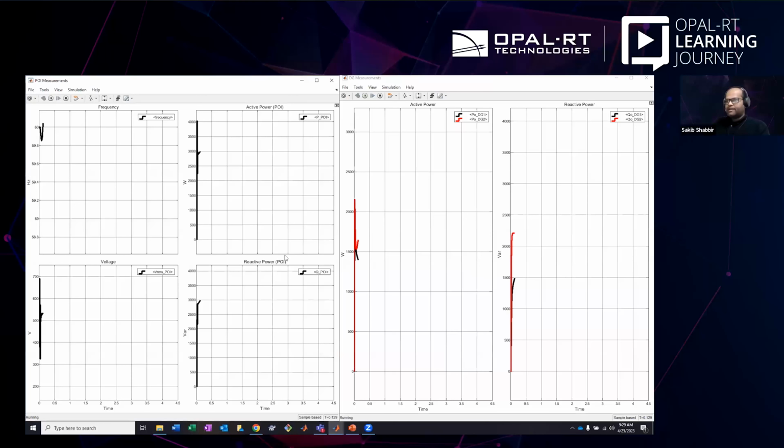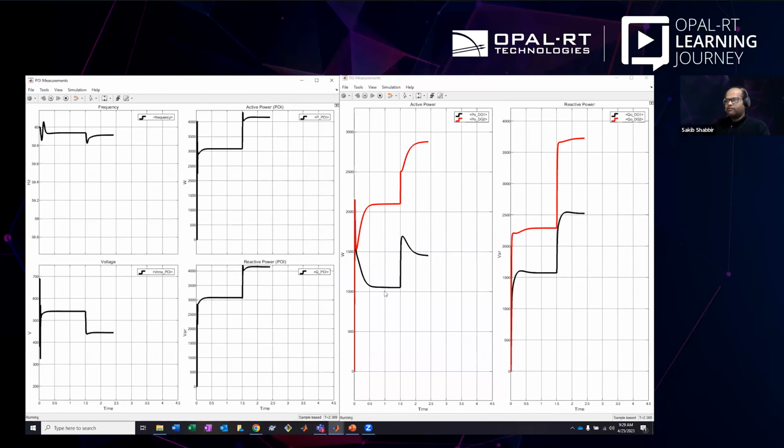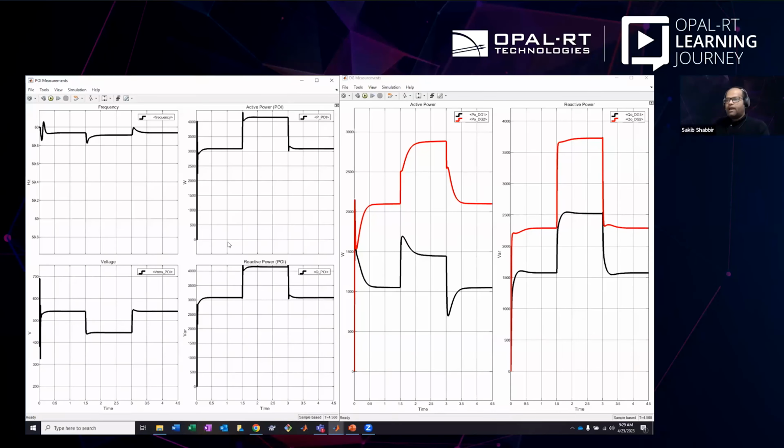Again, we can expect that with two DGs of two different nominal capacities, the power dispatch should be according to the ratio of the nominal capacity ratings. Again, even for VHG, the two control algorithms for DG2 dispatch twice that of DG1 for both active and reactive power. And according to the characteristics of the virtual synchronous generator, the frequency profile is significantly improved